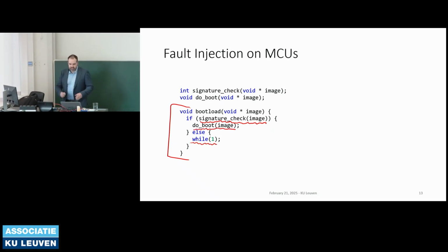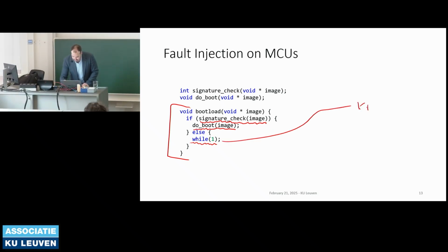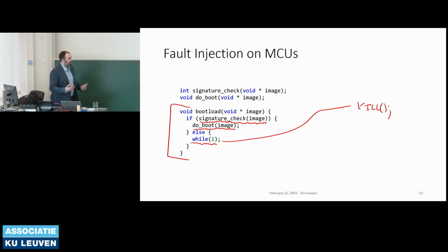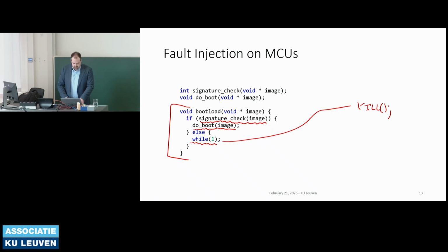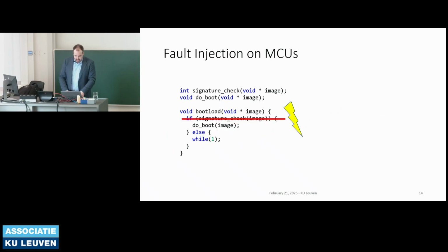So this infinite loop might be hidden away, perhaps in a kill function or something like that. But the point is, once the device realizes, oh no, I can't do anything, the signature is bad, I have to just wait. It might be waiting for a watchdog timeout, whatever it is, there's some point where it just starts to wait. So if we do fault injection, what we're doing is we're actually saying that we're able to modify the device, and there's many things we could do.